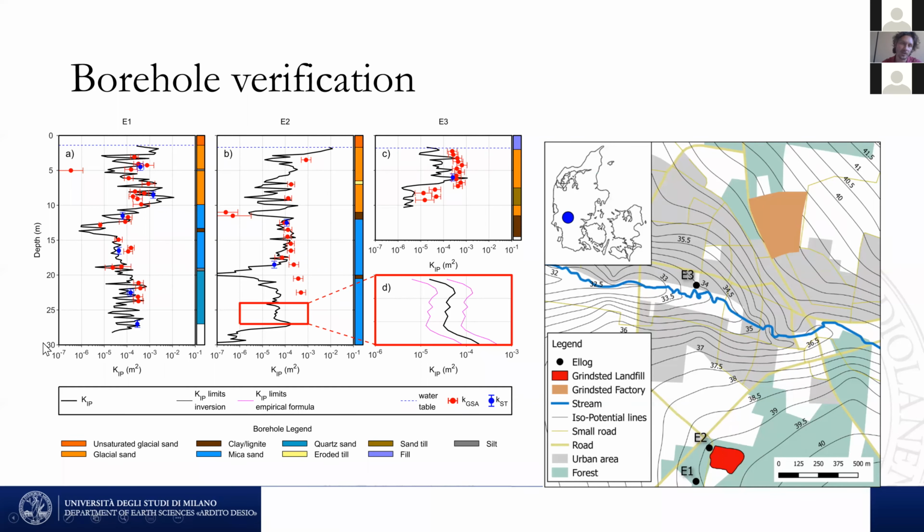As we see, as a function of depth, the trend of the estimation of the hydraulic conductivity follows really well the data from grain size analysis and slug tests in all the 3 boreholes, where actually the water conductivity was really different, but also the composition in terms of ions of the water. We have only a few outliers, let's say, but they do correspond to really, really thin layers that we were not able to resolve with this geophysical method.